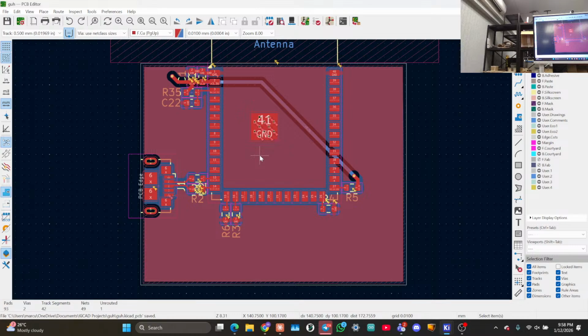Also, we didn't include it in the curriculum, but we'll do a hands-on lesson at some point about how to solder. That means regular soldering, also PCB soldering. We have the tools and equipment for that, so we'll teach you guys those if you want. And it's just easier to use one side only. Because if you've got both sides, then when you try and solder one side, the other side's components drop off. It's very annoying.